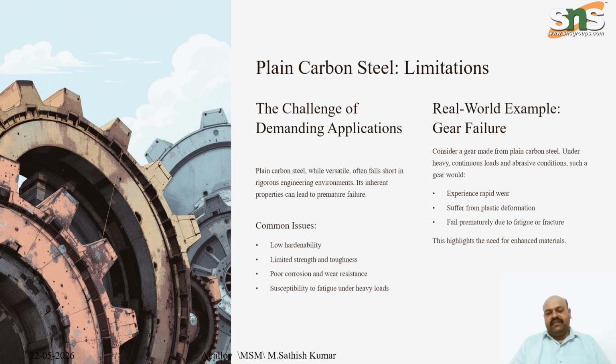That's why we have seen a larger gear here. What is the purpose of a gear? Yes, a gear is to transmit power from the engine to the tires in the automobile industry. And consider a gear made of plain carbon steel under heavy continuous loads and abrasive conditions. Such a gear would experience rapid wear, suffer from plastic deformation, and fail prematurely due to fatigue or fracture.